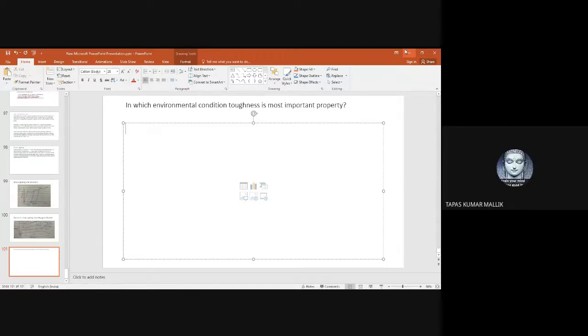Due to failure of the body. How did the body fail? Failure and fracture are different things. Has fracture happened or failure happened? Fracture. Yes, fracture has happened. So a crack formed. Why did that crack form? What is the main reason behind the formation of that crack? Because of transformation of austenite to martensite at low temperature.